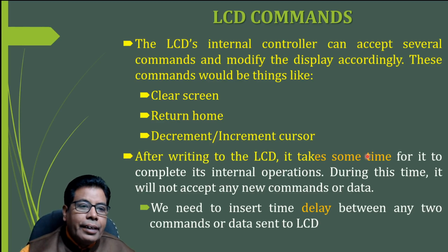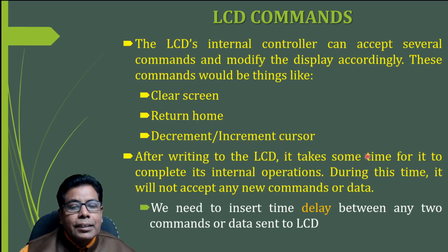After writing to the LCD, it takes some time to complete its internal operations. During this time, it will not accept any new command or data. We will have to wait. So that's why in the program we'll have to insert a time delay between any two commands or data sent to the LCD. Again, we are going to see this when we actually see the program.